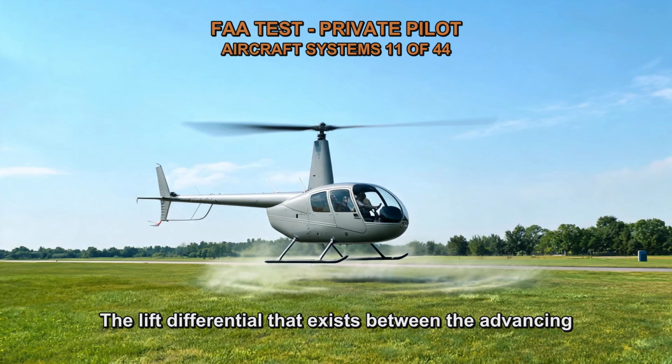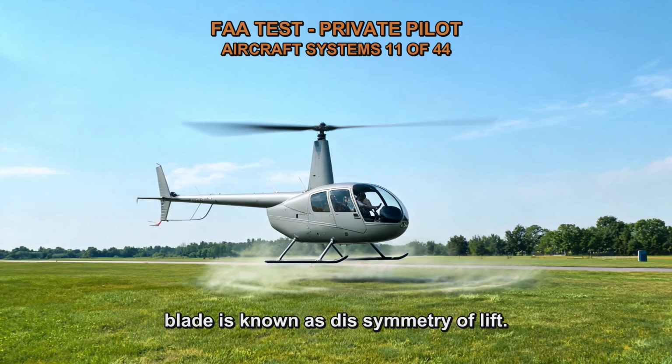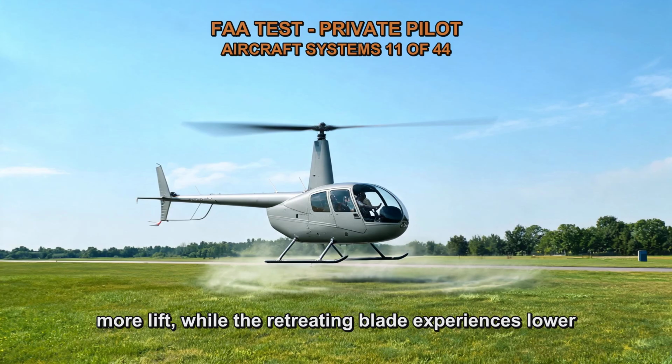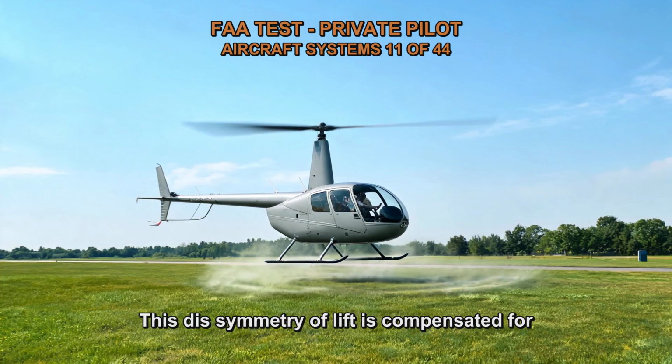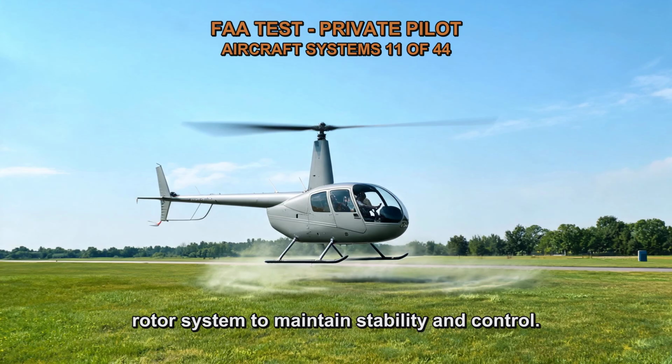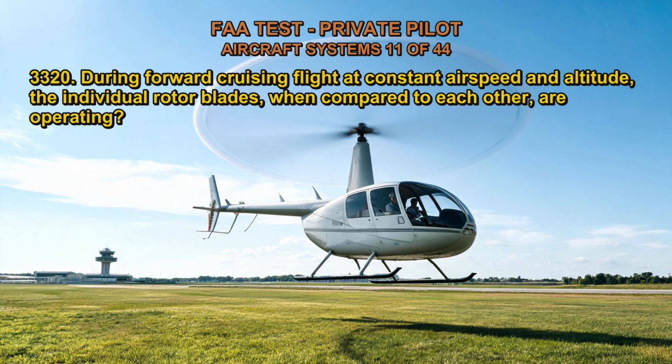The lift differential that exists between the advancing main rotor blade and the retreating main rotor blade is known as dissymmetry of lift. In a helicopter, as the rotor blades rotate, they encounter different airflow conditions. The advancing blade experiences higher airspeed and generates more lift, while the retreating blade experiences lower airspeed and generates less lift. This dissymmetry of lift is compensated for by various aerodynamic and control mechanisms in the rotor system to maintain stability and control.